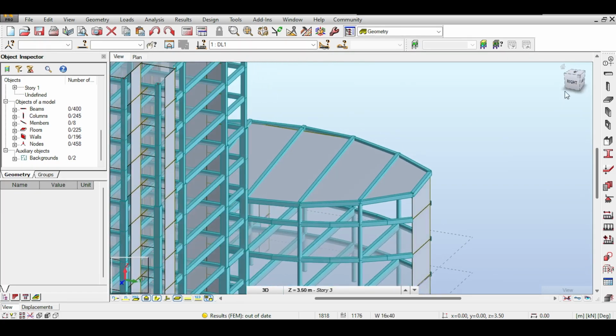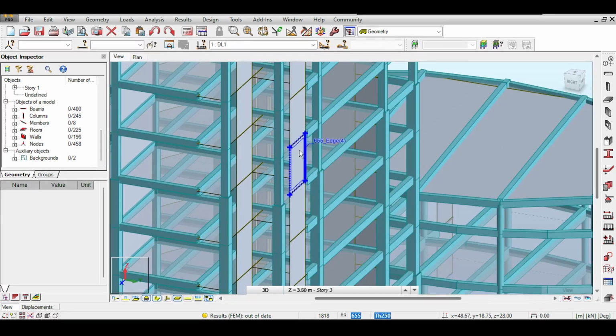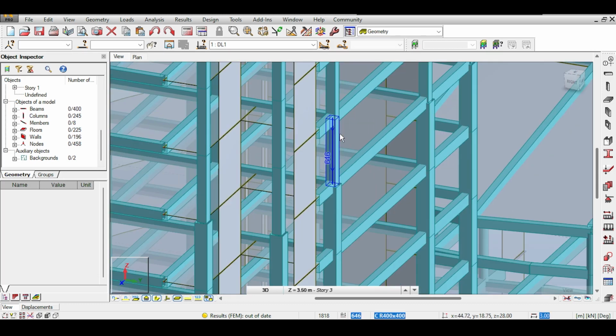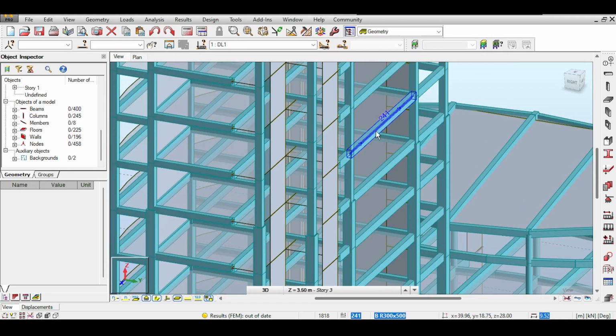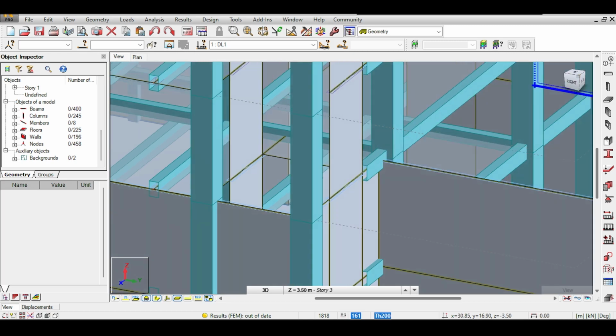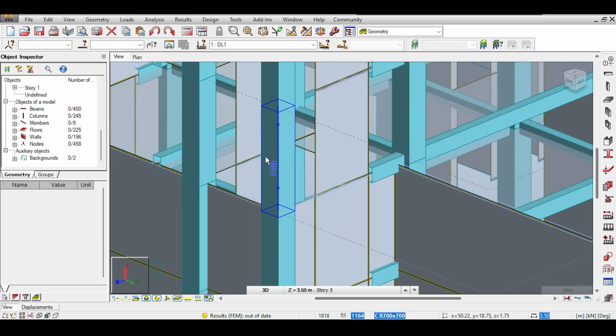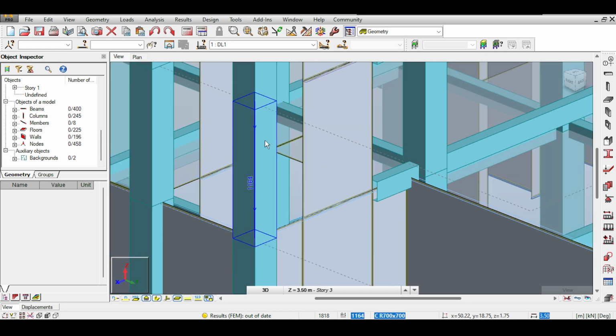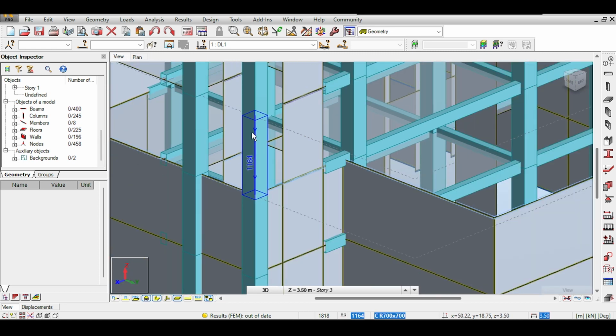Now, since I have columns, it doesn't make sense to have them like this flying, so I have to connect them somehow to the structure. So I would have a beam that is connecting it to the structure, or I can just rely on the staircase. I will leave it for now. Tell me in the comment section what you think. I think I should have extended the shear wall and put the beam in it, although it's gonna be a nightmare because you're gonna cast half of the shear wall. Nah, I think this is cleaner. I think this is cleaner.